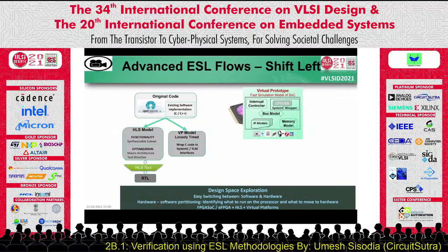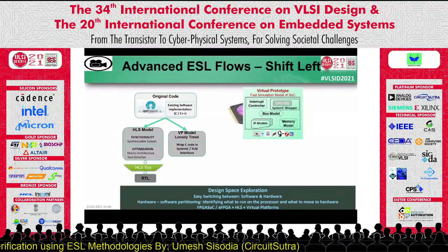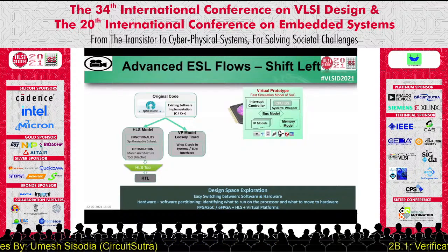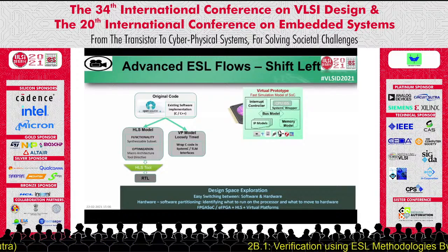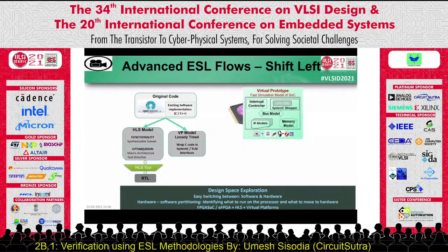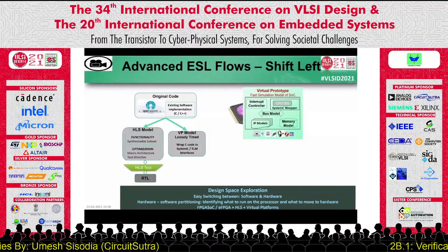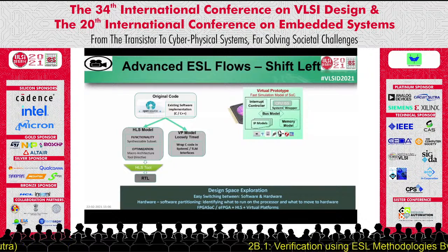Okay, so we talked about various use cases of ESL, like virtual prototyping, architecture exploration, and high-level synthesis. All these use cases require different kinds of models to be developed at different abstraction levels, requiring different levels of accuracy in functionality and timing. Using the right set of adapters or transactors, we can combine these different kinds of models in the same flow, thus enabling powerful shift left methodologies to be used across the complete life cycle of SoC design, from concept to final tape out.